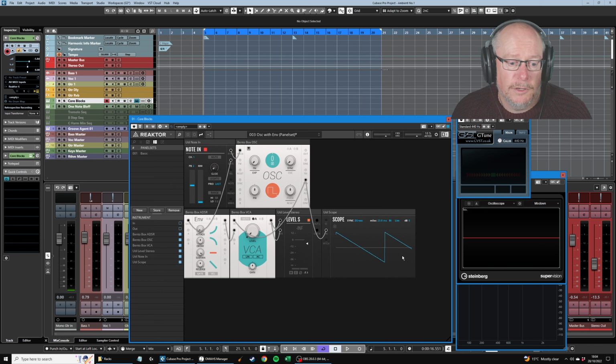The line represents 0 volts, and we have negative control voltages, and all waves operate in both directions. So with our square wave, which we're going to plug in manually now, we have exactly that behaviour. The control voltage is positive exactly the same amount of time as it's negative. Now this could be plus 0.5, minus 0.5, plus 1, minus 1, irrelevant.